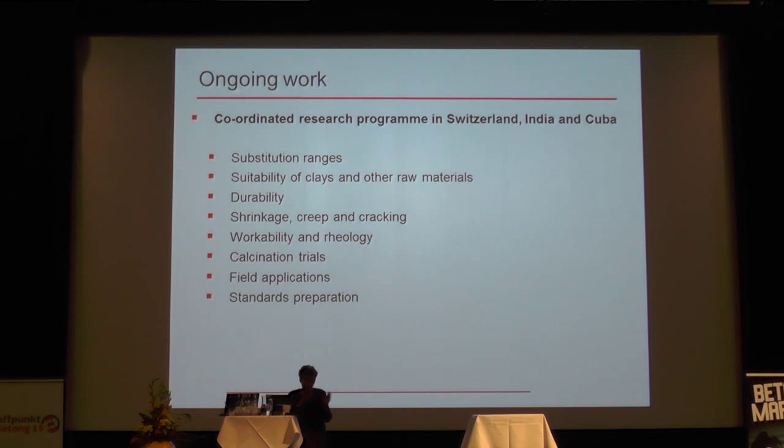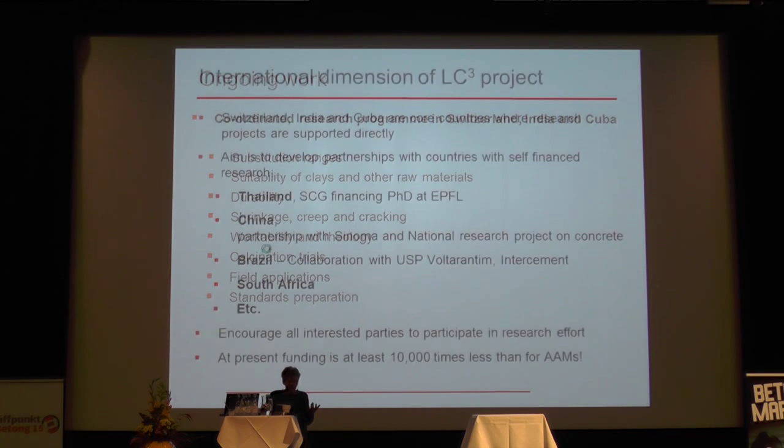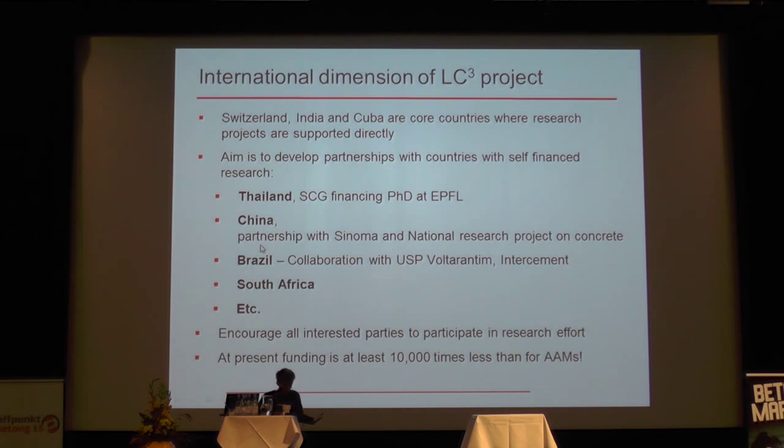So there's no reason why we expect the durability to be a problem. It has to be tested, it has to be examined. We have to look at things like shrinkage, creep and cracking. Again, we started work on that. First results look very positive. We have to look at workability and rheology. Sometimes this can be an issue, but most of the time you can make perfectly good concrete without any particular change in the formulation. So this is all ongoing, and it's really an international program.